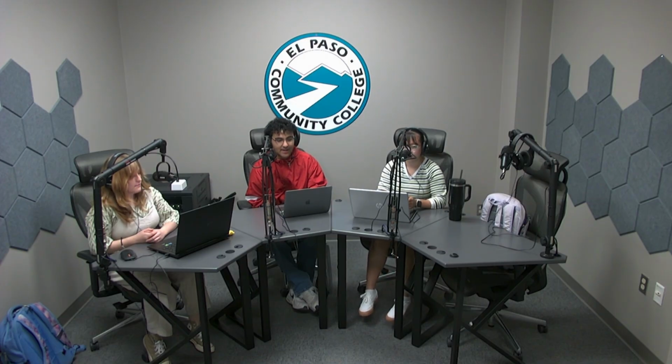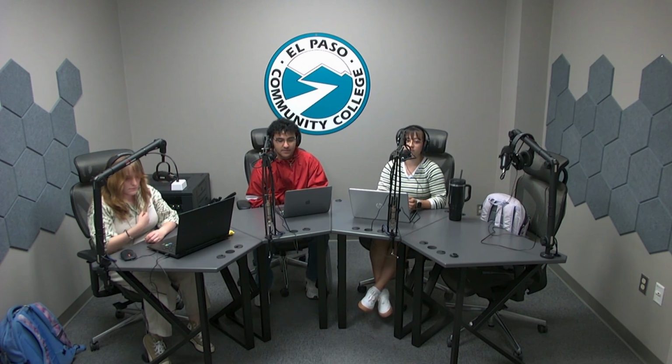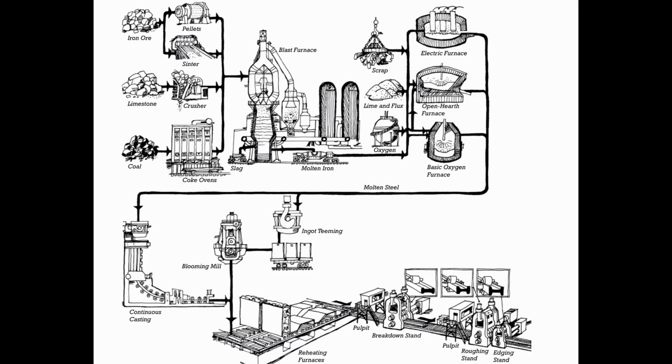The process of converting iron ore to steel begins with the smelting of the ore into cast iron, which is what we talked about earlier. This is done in a blast furnace. Regardless of the particular steelmaking process, finished steel is cast continuously into what we call beam blanks or blooms, which are then rolled into final form.